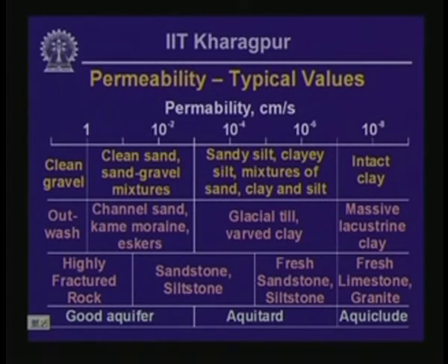On the other hand, intact clay, massive or lacustrine clay, fresh limestone and granite are not likely to conduct any groundwater movement at all for any practical purpose. So, they qualify as aquicludes. Just have a look at these values, because there is a lot of information presented on this slide before we move on to the next topic.